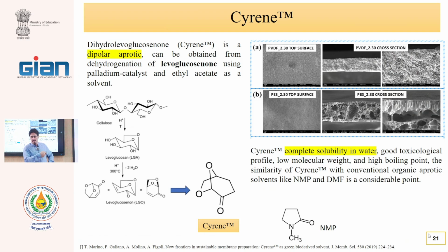I have some studies about the use of green solvents in membrane fabrication. The membrane is good, the flux is good, but the stability is low. In papers, maybe they do not mention it, because everybody wants to say that our membrane is good, but our results show that when we use a bio-based solvent, for example Cyrene, the resulting membrane has 50% lower tensile strength.